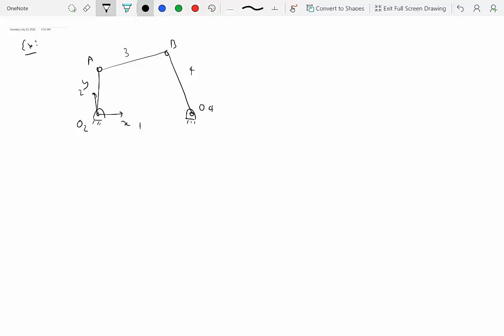And we have the length of the linkage system given to us. So let's say this is L2, this is L3, this is L4. We also know that initially the angle this is making from X-axis, let's say that's theta 2. We also know the angle that this is making from X-axis, theta 3, and we also know the angle this is making from X-axis, let's say theta 4, right? So this is the linkage configuration at a particular instant. Next instant there will be a different configuration. The lengths will be same, but the orientation of the links may not be same, right?